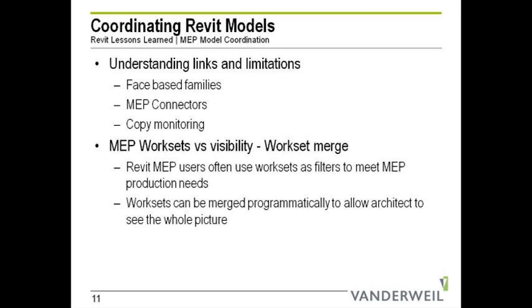They're linked. And so now I can have linked things that move with each other, but I can now connect to them. I can see how their load affects the building load. I can use the MEP systems, such as hydronic piping, airflow, power, switching, those kind of systems that MEP needs. I can now use those with an architectural model.